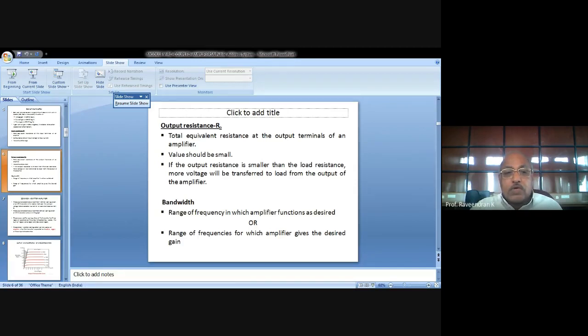Now you give your input signal between the base and the emitter. That is shown here. That's an alternating signal. Now we will see what happens. On the DC quiescent operating point, we superimpose the AC signal by the application of an AC sinusoidal voltage, an audio signal, which is essentially an alternating signal, isn't it? At the input side. Due to this, the base current varies sinusoidally.